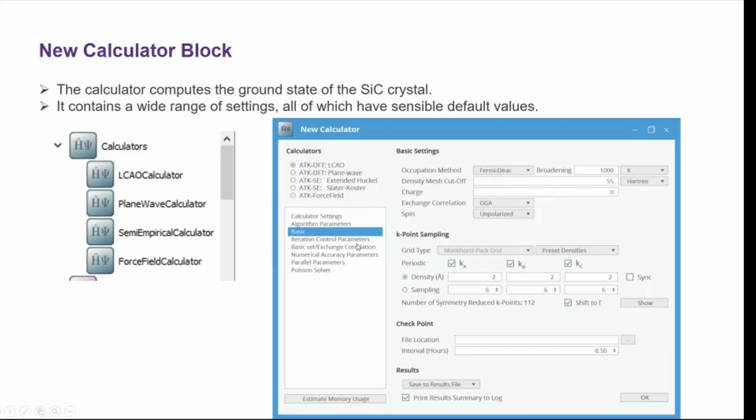Now for this you have to choose the basic parameters, which are Ka, Kb and Kc. These are the lattice values, the K point values. That means along which axis your points will vary; the higher the value, the more accurate the result. So we have to select the density. The sampling density of 2 2 2 has been chosen by default.